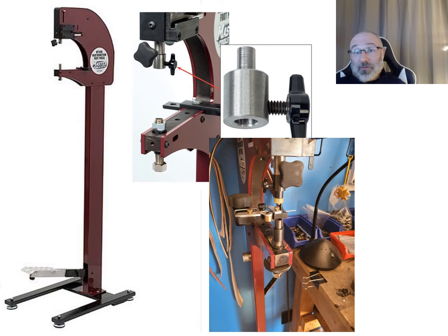So we talk about different presses, different types of tools to utilize these. This is my multi-function press that I have here. Here's the manufacturer's picture of it, and this is great because it's a foot press. Before I talked about needing to use both your hands to hold things, and sometimes you can't let go to pull a manual lever. This one has a foot lever, so we get a mechanical advantage through here, and up top here for another mechanical advantage, and this pushes down when you step on this foot pedal right there.